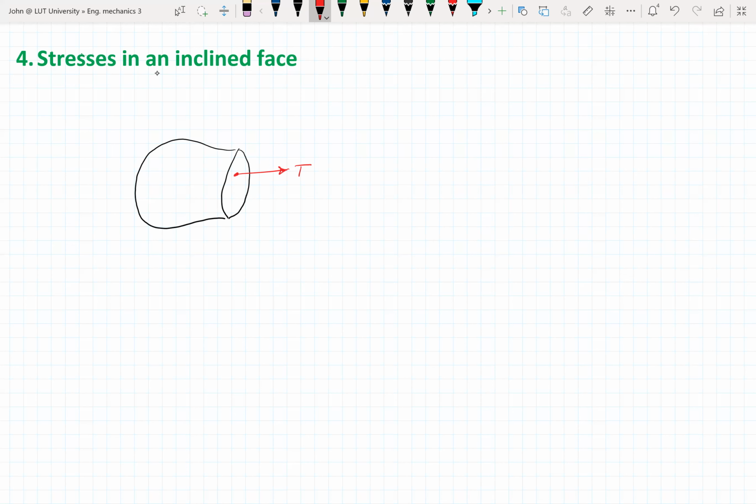And the other plane, or this inclined plane, is going to have two main vectors that define the plane. As we have been using this convention of normal stresses and shear stresses, I'm going to draw the same convention here. I'm going to have a small plane here, and from it, two unit vectors coming out. So it's going to be this normal vector. And I'm going to have a tangential vector that I'm going to represent with the same symbol of the shear stress.